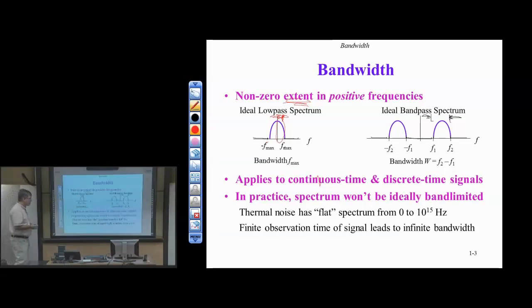So in practice, the spectrum won't be ideally band limited. There are more than two reasons, but I'll give you two reasons why this isn't going to happen in practice. This is wonderful theory. It's a good starting point, but it's not the ending point. One is thermal noise has a flat power spectrum that goes to pretty high frequency, out to 10 to the 15th hertz.